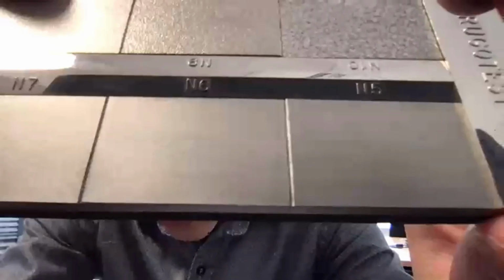The same type of etalons you can have for different types of processes. So this is for spark erosion. As you can see, the fingerprint is very different. Now it's very evenly distributed in all directions, while previously it was very well organized in one direction. And yet again, you can see how from the rougher example we are getting to the smoother one here. And yes, this is the first way to check roughness, if you have specific etalons like this.